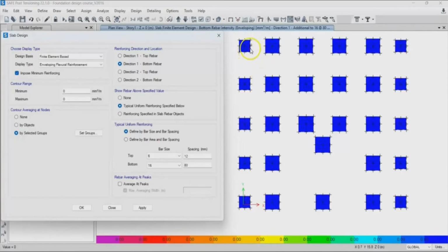As you dig out the dirt from this footing, you're also digging out dirt from the next one. If there is not enough space, then where will you place the soil? It is going to be very, very difficult for the excavator to dig out the soil. And also, one of the main reasons why we place this 50% threshold is because of the formwork and the labor costs.